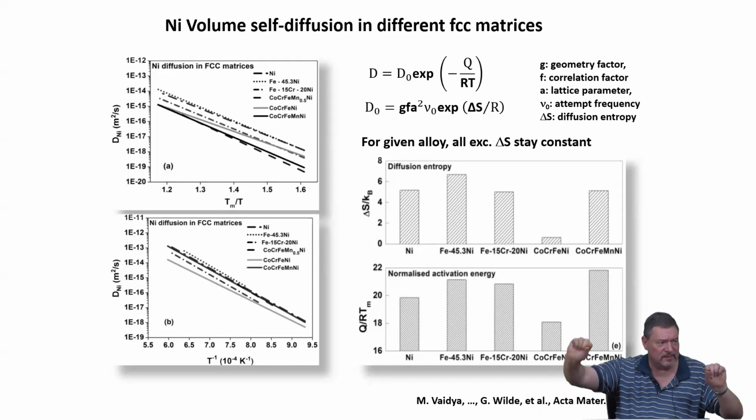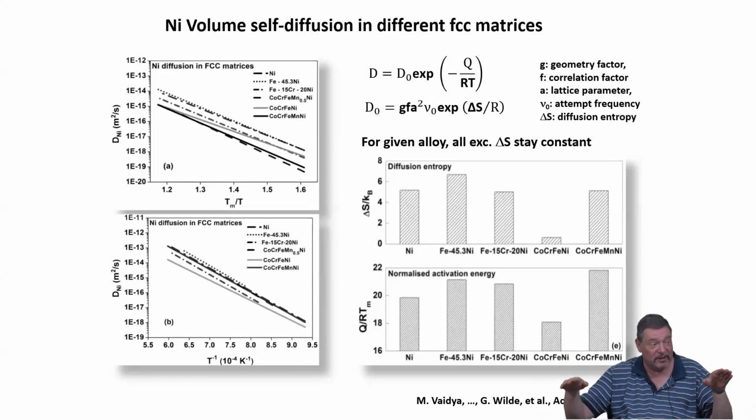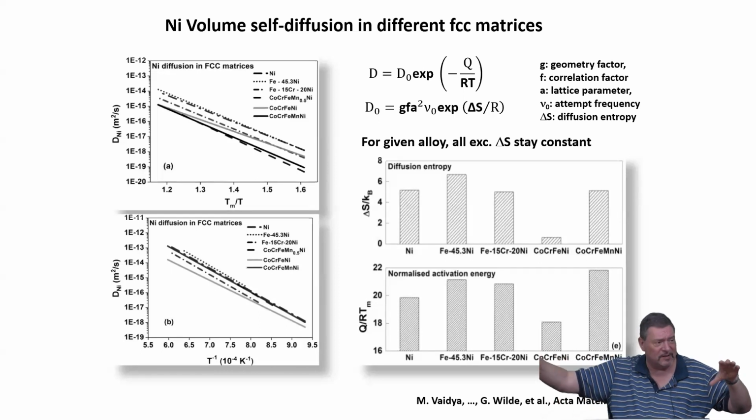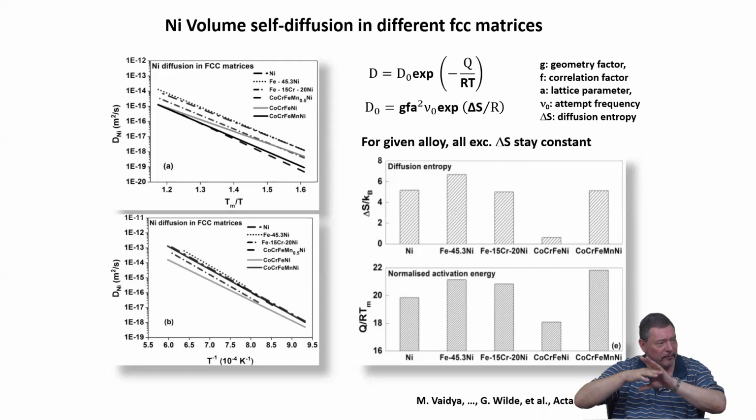If this splitting distance is large, there is a good probability for another split dislocation to interact with this split dislocation. And then basically a lock could form, which means there is a dislocation-dislocation interaction forming a product which can no longer glide because it has a Burgers vector which doesn't agree with the lattice it's in. And this is stabilizing the dislocation structure.